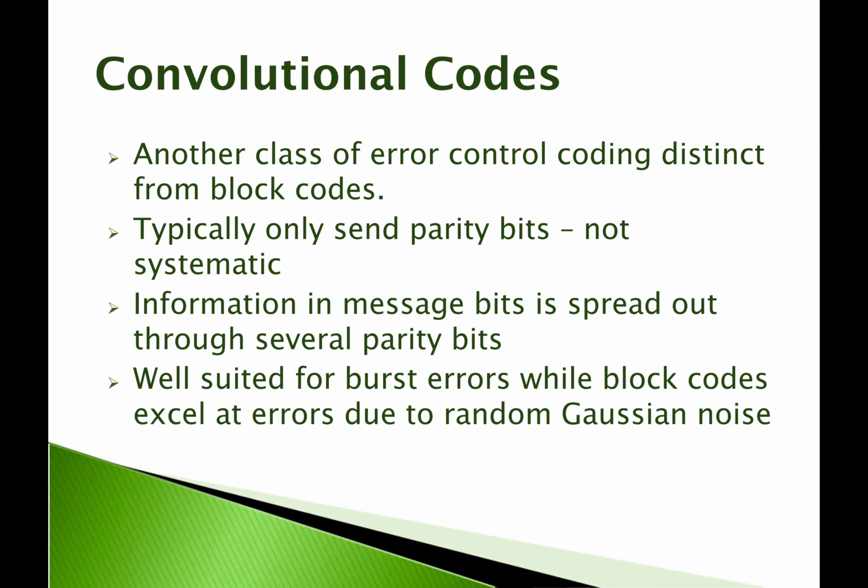It could also be some momentary interference at high frequencies, HF, which ironically are now considered very low frequencies because we do so much of our work in the microwave region. But HF is more like around 3, 7, 10 megahertz, and there lightning interference is a big deal, right? So these types of interference can affect multiple bits in a row.